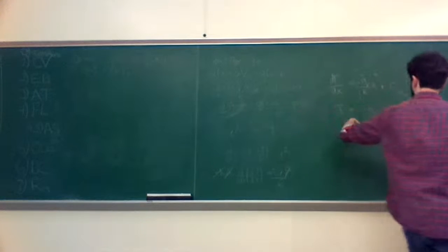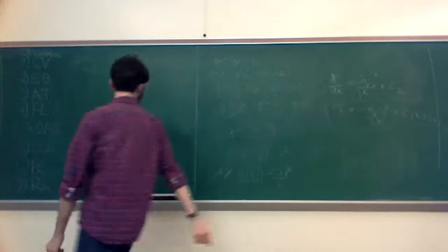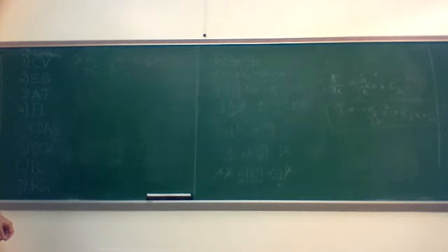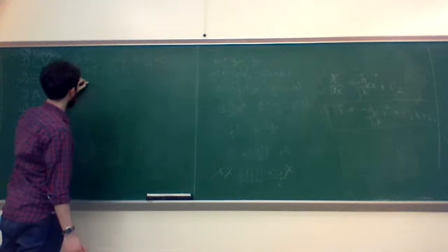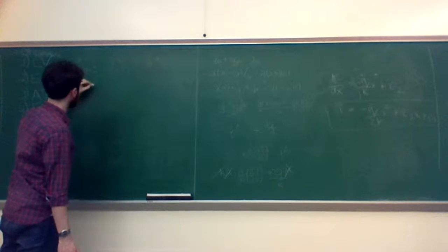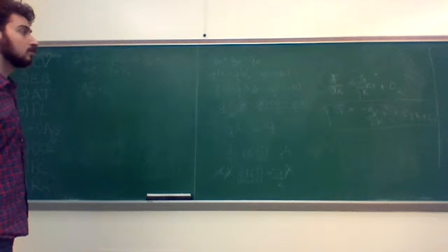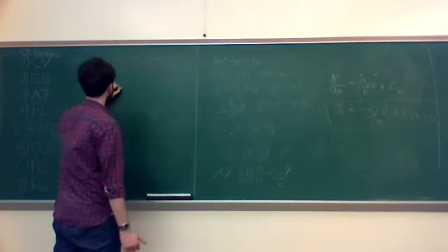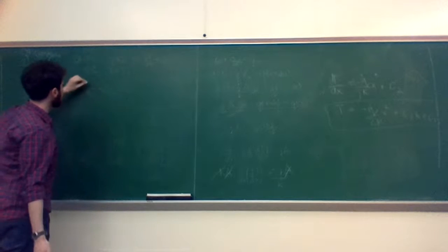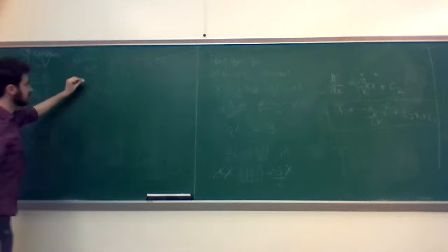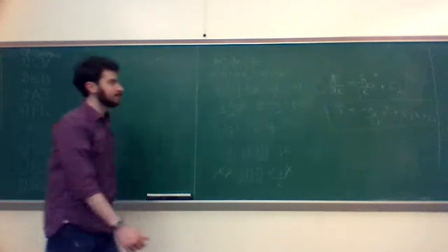So this is our final temperature distribution pre-boundary conditions. So what is dT/dx of that? It's going to be just negative q dot x over k plus C2. Negative q dot x over k plus C2 equals 0. Now, that's only at x equals 0, right? So let's just replace that x right now with a 0. So if that x is 0, this whole term goes to 0. So now we just know C2 equals 0. Boom! Insulated boundary condition. It's magic.